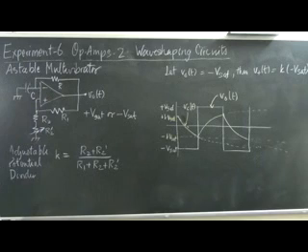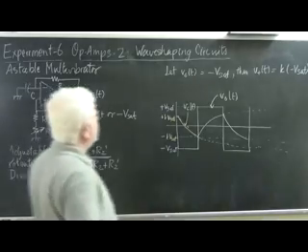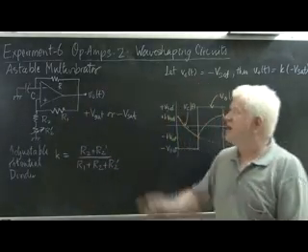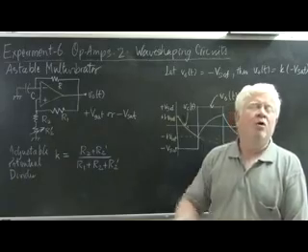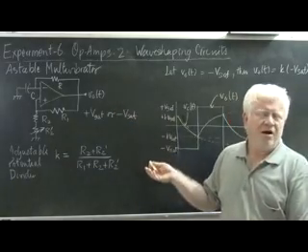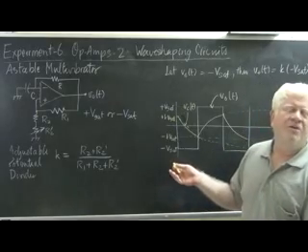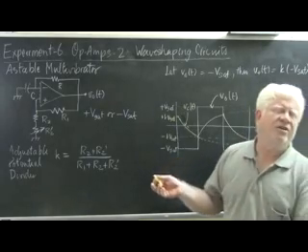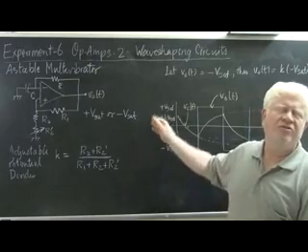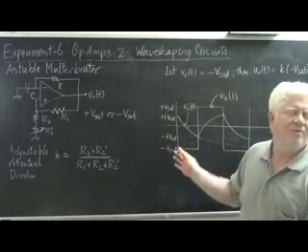The other way of course is to change R and C so that the time taken by the charging circuit of RC to achieve that voltage is altered. So for example, if you choose a larger value of R and C, the frequency of the oscillation will come down.